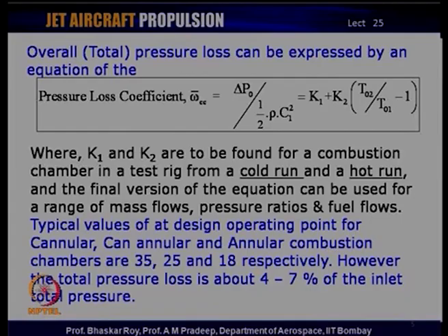Now, the cold run gives you the fundamental fluid mechanic losses and helps you quantify what the basic losses are notwithstanding any combustion phenomenon. The second one is directly related to the combustion phenomenon, and hence, if there is a temperature rise, there is going to be a certain amount of pressure loss, and that is called, as we said, combustion related pressure loss. So, the first one is fluid mechanic pressure loss, the second one is combustion related pressure loss.